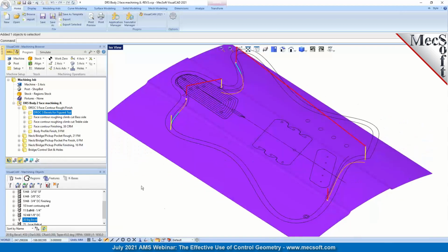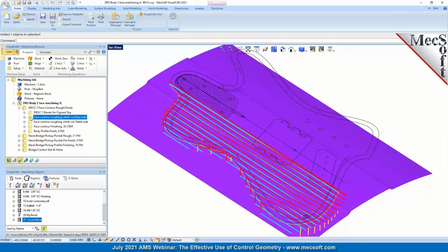If you go back and watch the video, if you go back to the slide where we showed this, you'll see that there was an engraving bevel here, some engraving in the front areas. So this is how they controlled that. They knew exactly where the tool needed to go. They drew the curve, and they used an engraving operation.